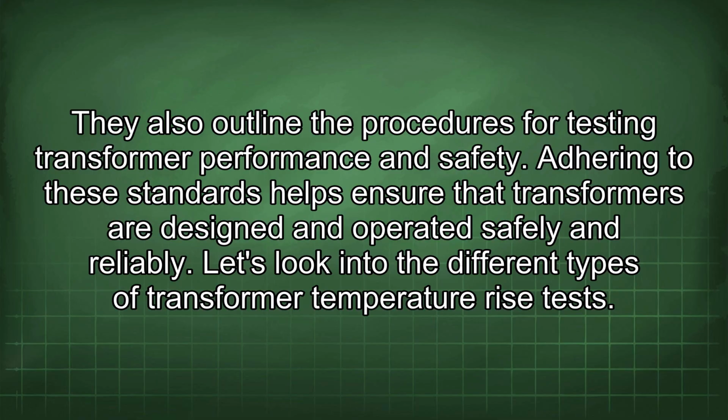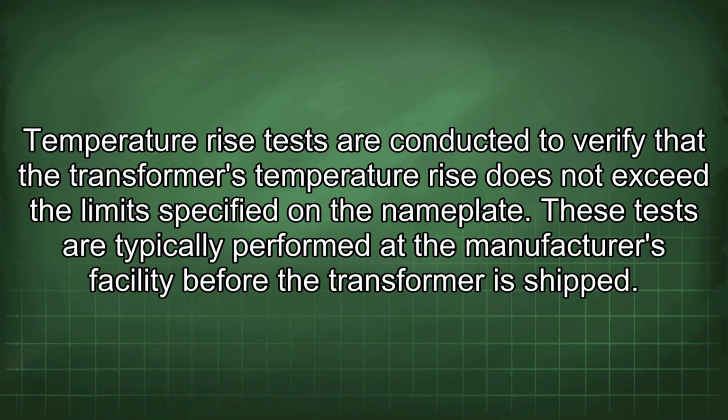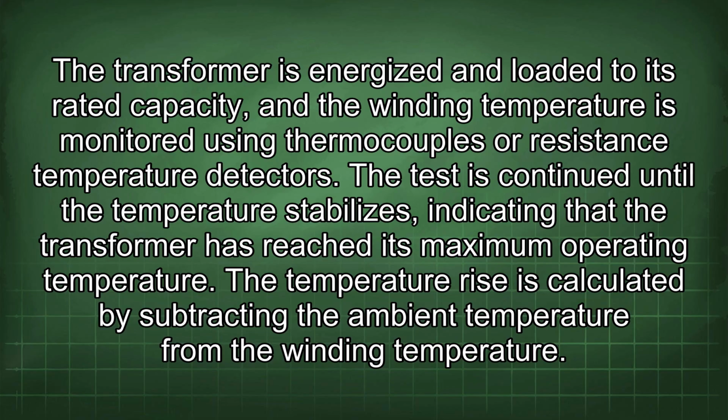Let's look into the different types of transformer temperature rise tests. Temperature rise tests are conducted to verify that the transformer's temperature rise does not exceed the limit specified on the nameplate. These tests are typically performed at the manufacturer's facility before the transformer is shipped. The transformer is energized and loaded to its rated capacity, and the winding temperature is monitored using thermocouples or resistance temperature detectors. The test is continued until the temperature stabilizes, indicating that the transformer has reached its maximum operating temperature.